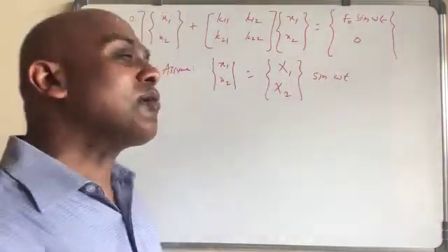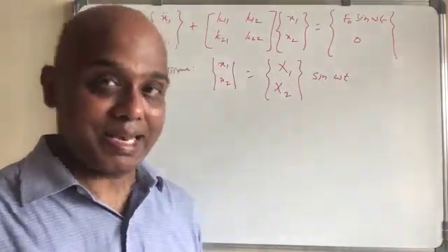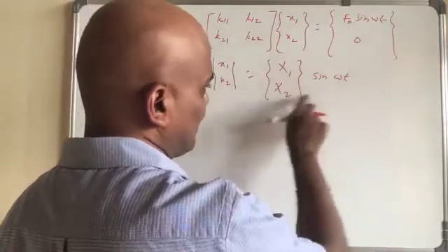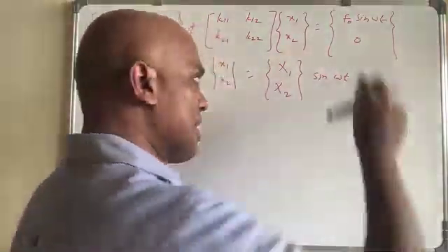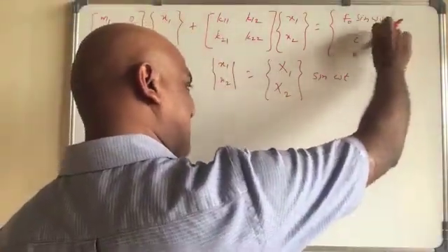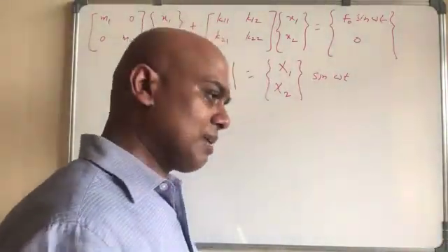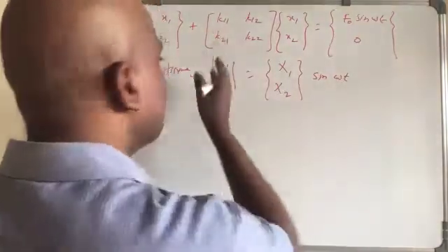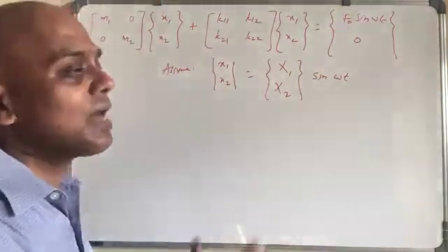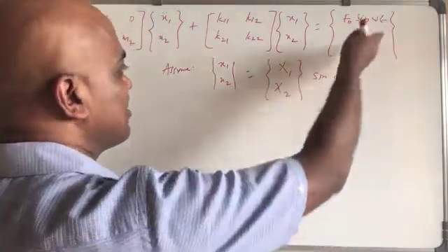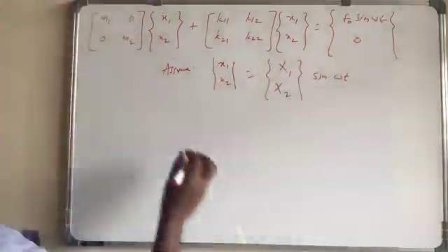For a 1 degree of freedom system also we have seen this: when the force is of this type, the solution is also of this type. There is not even a phase difference, because the phase difference comes because of the damper. This is an undamped vibration problem, hence there is no phi, or phi equal to 0. So the solution will be like this.